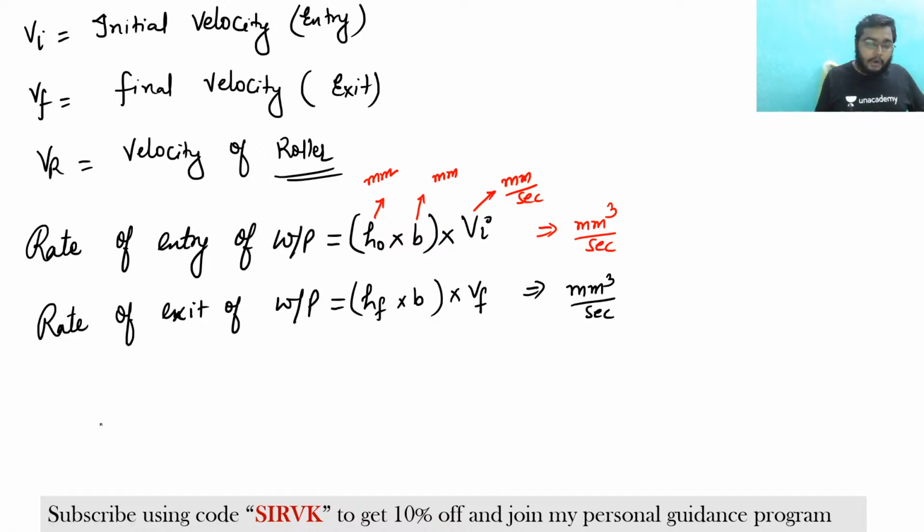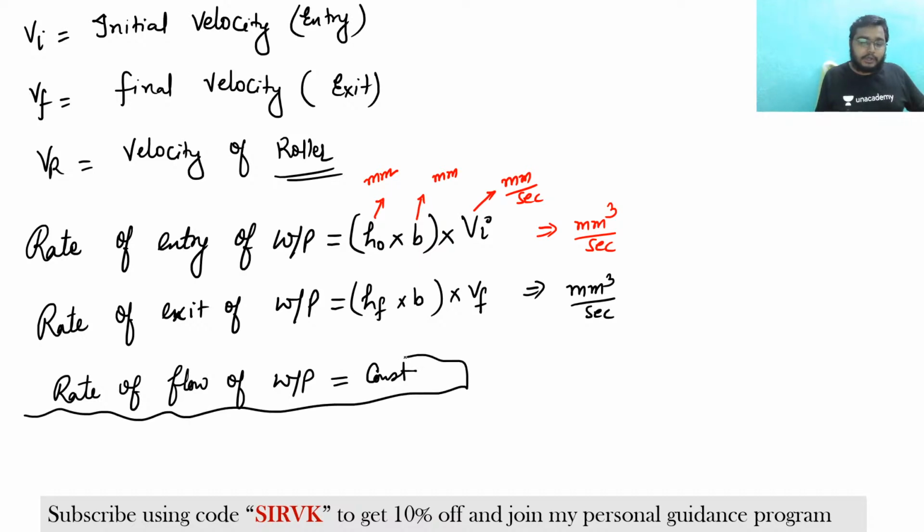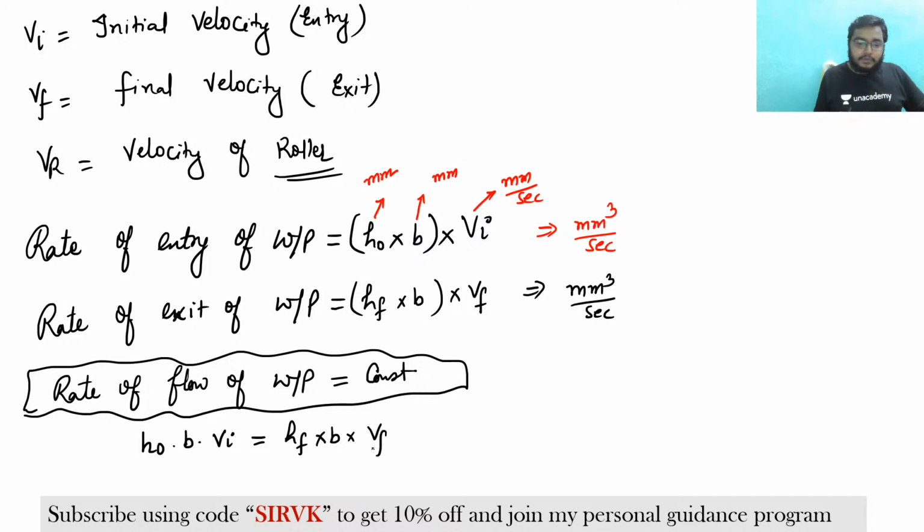And one most important thing: the rate of flow of the workpiece should be constant throughout the rolling operation. This is the most important condition. So if this is the condition, can I say that h naught b Vi is equal to hf into b into Vf?